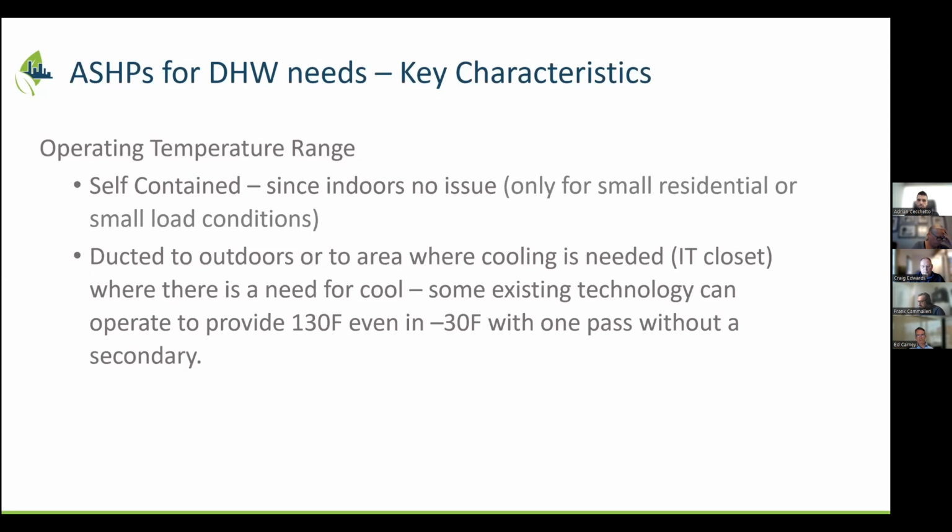Well, I guess when you look at the heat output from any of these heat pumps, you need some pretty good tonnage to accomplish the kind of heat that you need for domestic hot water. It's a pretty big load, or it can be. And the small ones that you put right in the mechanical room are great if, like you say, you have the space and you have the heat gain in a mechanical room. But I would think for most applications, you have to be careful with that because they can quickly overcool the mechanical room. So what we're seeing mostly is larger systems that are outdoors. It looks like a condenser located outside, and the domestic water is directly piped out, and you have to heat trace it. That's typically what we're seeing.